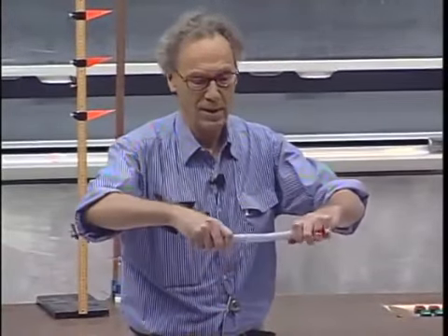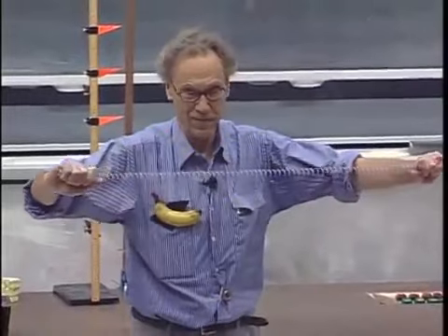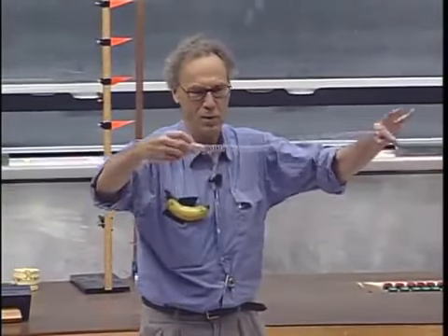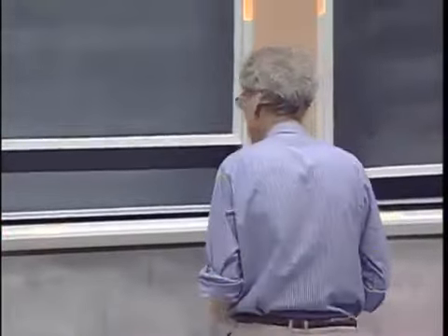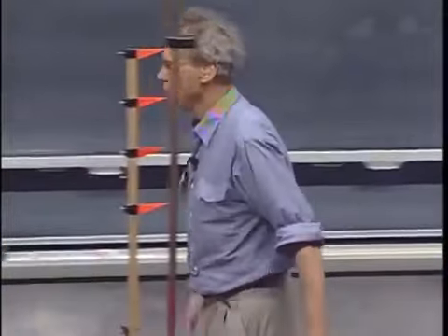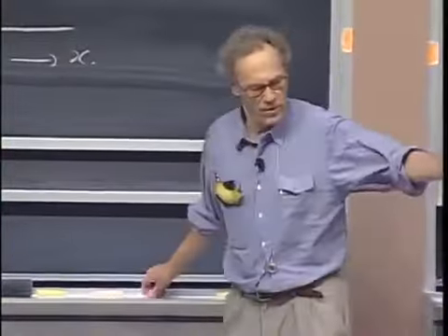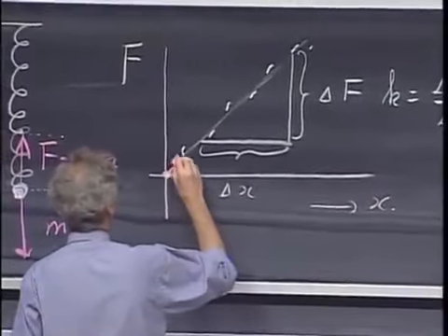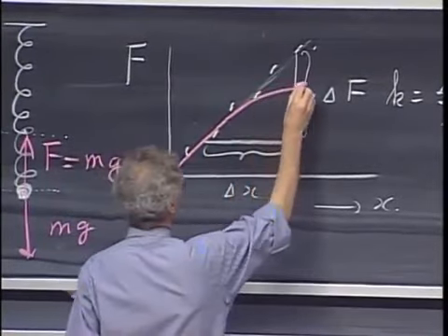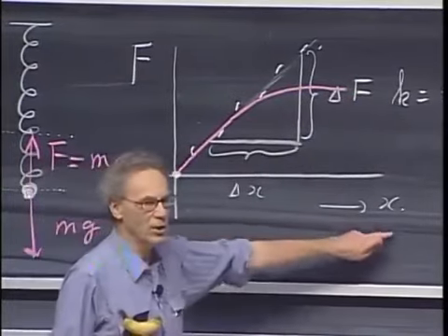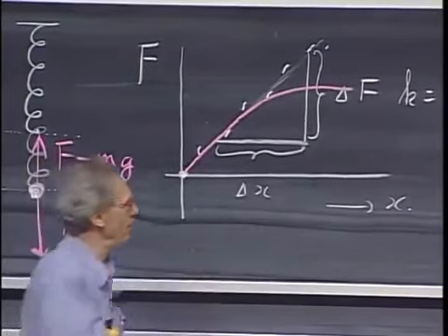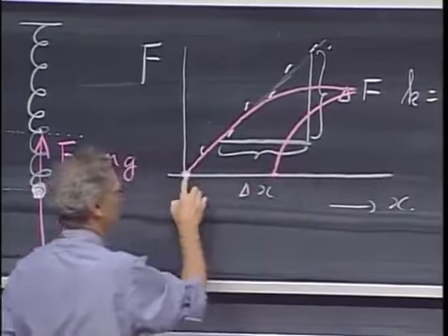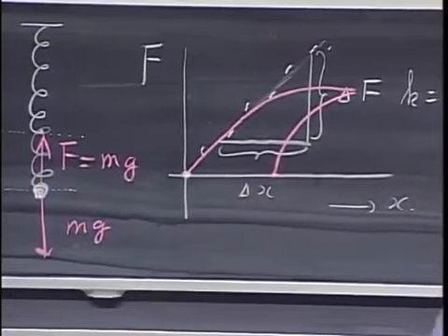I can do permanent deformation. Look, that's easy. For sure, Hooke's law is no longer acting. Look how much longer this spring is than it was before. So there comes, of course, a limit how far you can go before you permanently deform the spring. What I have done now with that spring, probably in the beginning, I went up along this straight line, and then something like this must have happened. I got a huge extension. My force did not increase very much. And then when I relaxed, when I took my force off, the spring was longer at the end than it was at the beginning. So I have a net extension which will always be there.